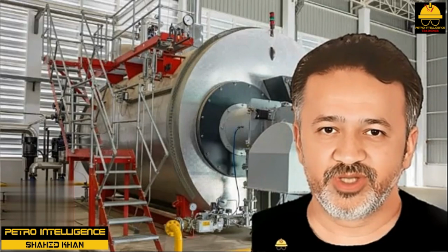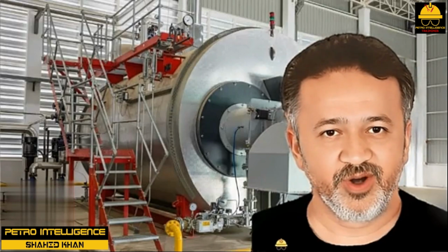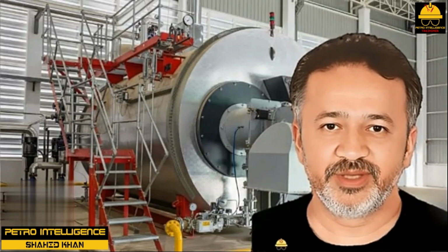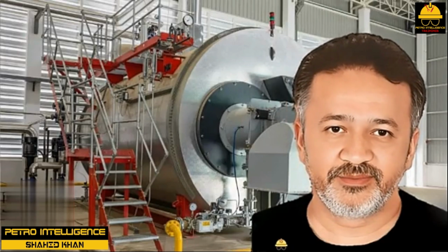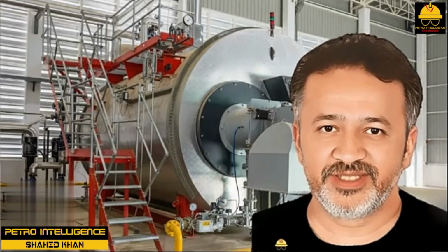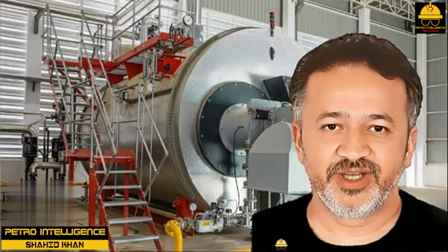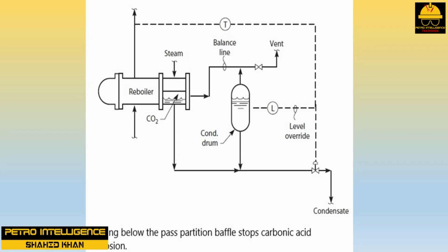Carbonic acid corrosion. Steam produced from demineralized water is largely free of carbonates. Steam produced from lime-softened water will be contaminated with carbonates that decompose in the boiler to carbon dioxide. As the steam condenses in a reboiler, the CO2 accumulates as a non-condensable gas. This gas will be trapped mainly below the channel head pass partition baffle, shown in this picture. As the concentration of CO2 increases, the CO2 will be forced to dissolve in the water.